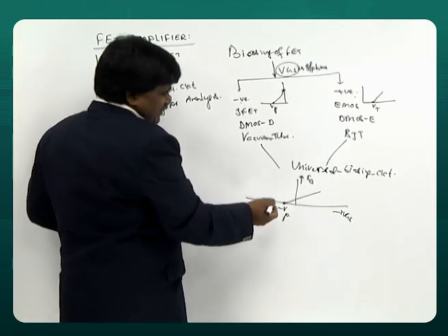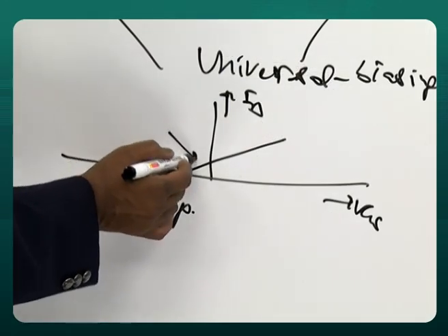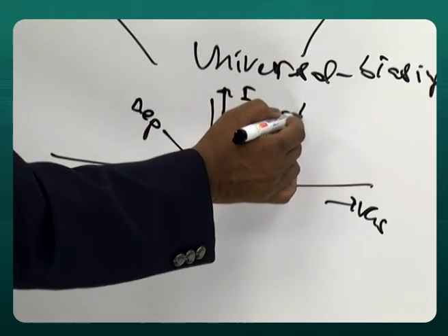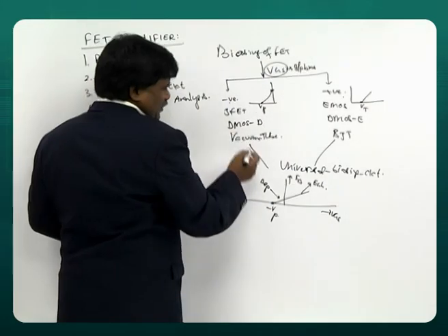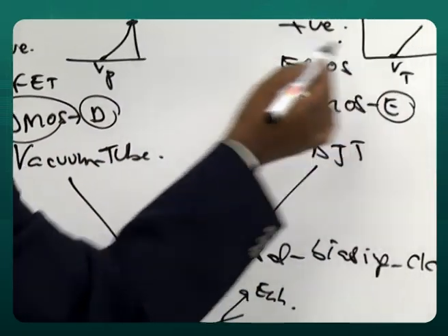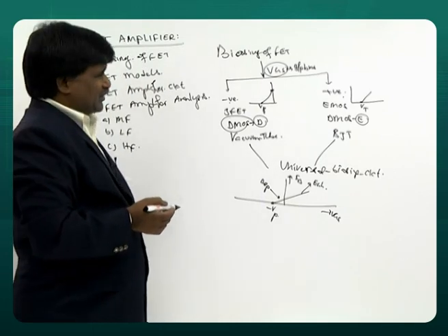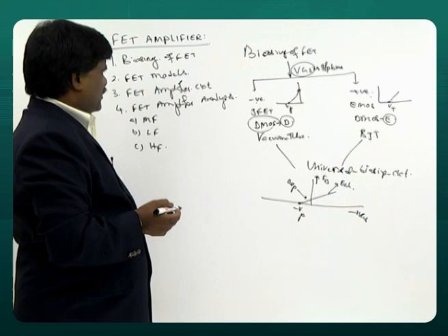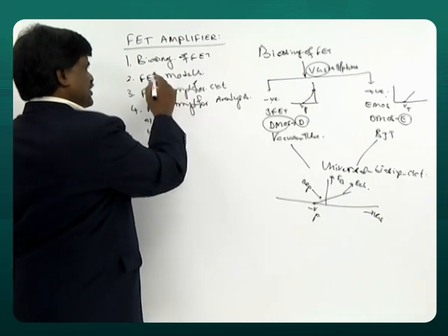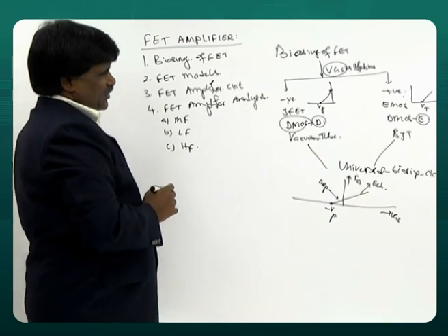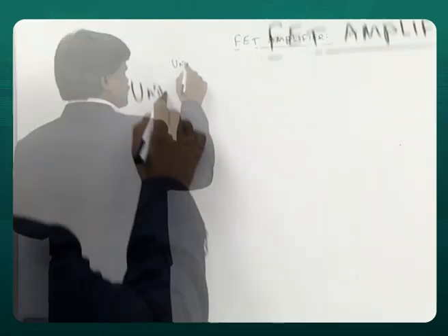That's why I said when this is decreasing, it is called depletion mode. When it is increasing, it is called enhancement mode. So depletion MOSFET has a depletion mode and enhancement mode. So two modes are there. That's the meaning. Now let us see the actual circuit.